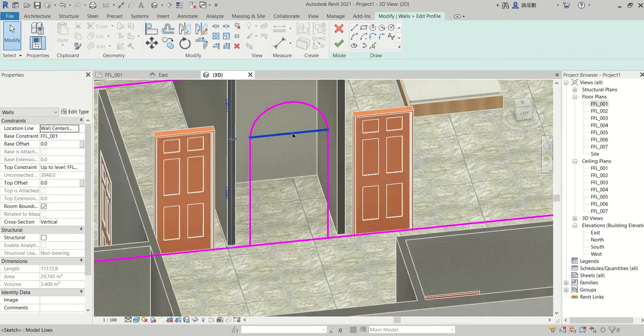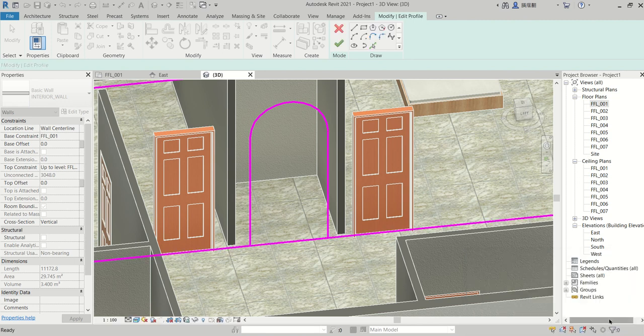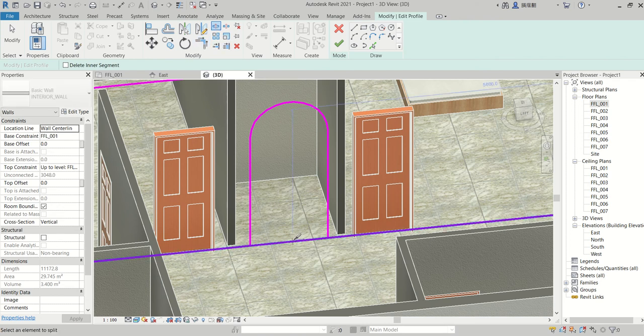As I already mentioned, this pink line should not have any intersections or gaps. So this is an intersection, right? I need to cut this off. So I choose trim. If I directly trim it, what will happen? Entire line will be deleted. So this line also will be deleted. So let us choose the cancel. Before that, I will split the element here. Split. Here in modify tab itself, you can see split option. Cut this somewhere,